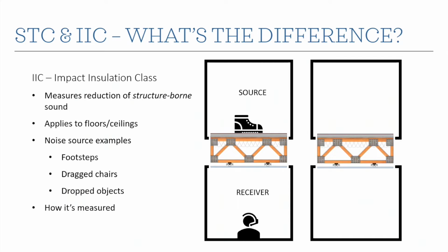The IIC stands for Impact Insulation Class, and it measures the reduction of structure-borne sound. And when we're talking about structure-borne sound, we mean sound that originates with an interaction with the structure. So the most common example of this would be footsteps, right? We step on the floor, we step on the structure, and we create sound. Other examples could be a piece of mechanical equipment that's tied into the structure and makes the structure vibrate.